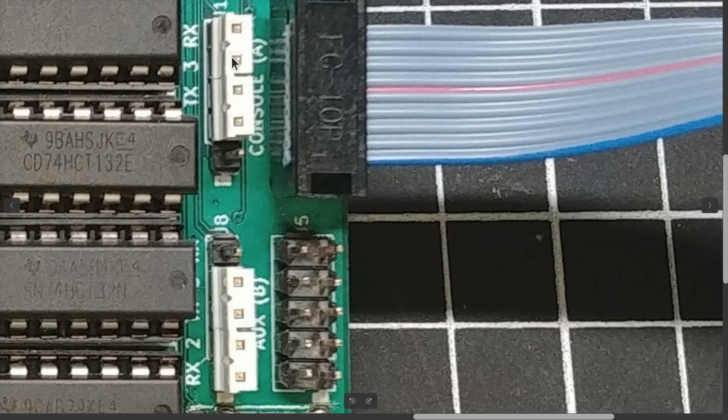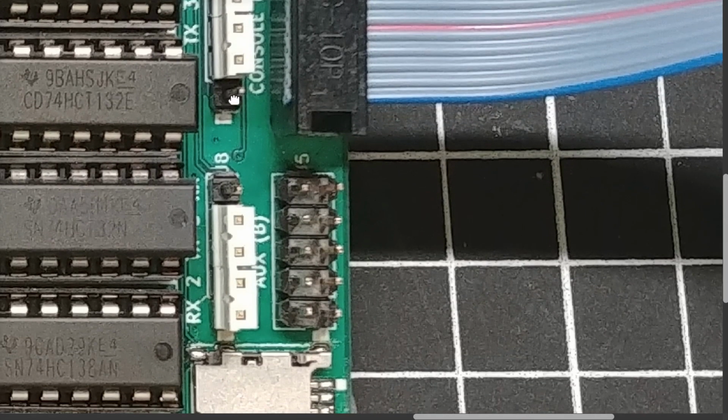Same thing is true for pin 3. It can be jumpered to either go to the receive signal in the retro board, or if you move this jumper to connect these two pins like I have down here, then pin 3 on the DB9 will be connected to the transmit signal from the SIO. Notice that receive from the SIO is hooked both to this pin way over here as well as the one way down here, okay, as you can see them marking down here.